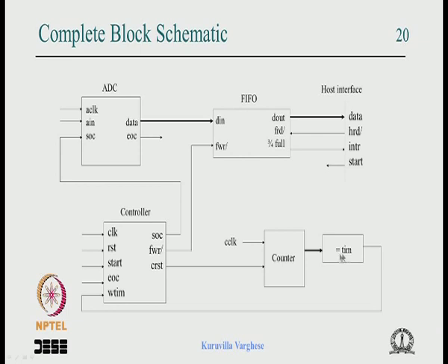When you say equal to some fixed value, it's a decoder, and equal to a variable, it's a comparator. So when you see equal to some numerical value, don't think that it is a comparator, because the comparator is an exclusive OR gate comparing. But when you say equal to 3, equal to 10, it's like, if you have 4 lines here and you say equal to 10, it is decoding the 1010 pattern. So you can imagine 1, then an inverter, then another inverter going to an AND gate, and that output is going to the controller.